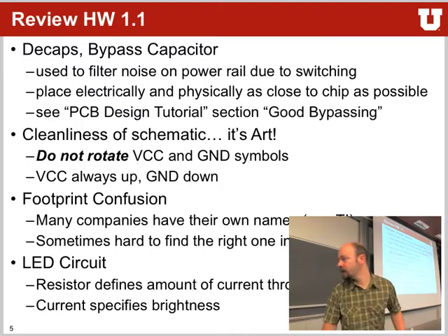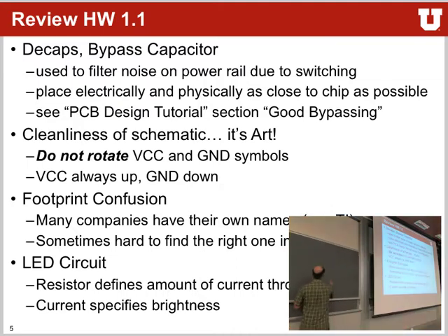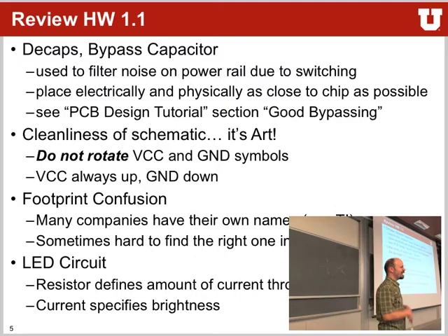If you see the symbols, VCC goes like this, and grounds go like this. Never ever have one of these signs that go like this. It's really confusing. All right? So this is a big no. Again, it's electrically correct. It's just not good practice.